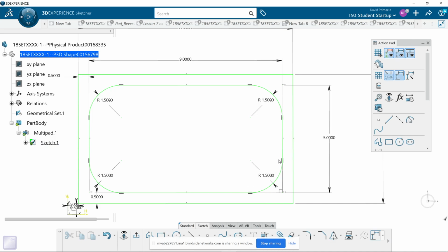Same. This is why I suggested I always make my curves counterclockwise, so that they show up as positive values when you analyze them, and it goes in the natural direction that CATIA wants to create them. Okay?